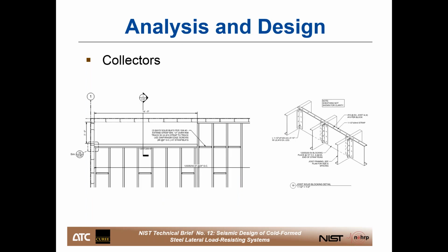So collectors are critical elements in the seismic load path and are required in S400 to be capacity protected. So collectors, of course, are the part of the system that are gathering the seismic force and carrying it to your strap brace wall or your shear wall, for example. That's why they need to be capacity protected, because they're not part of the body of the diaphragm like the membrane or the cords. They are a direct line from seismic force to seismic resistance. So capacity protection is very important.